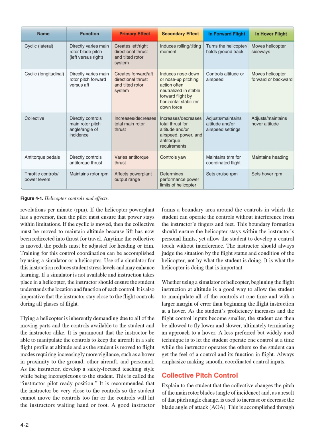This is called the instructor pilot-ready position. It is recommended that the instructor be very close to the controls so the student cannot move the controls too far or the controls will hit the instructor's waiting hand or foot. A good instructor forms a boundary area around the controls in which the student can operate the controls without interference from the instructor's fingers and feet.